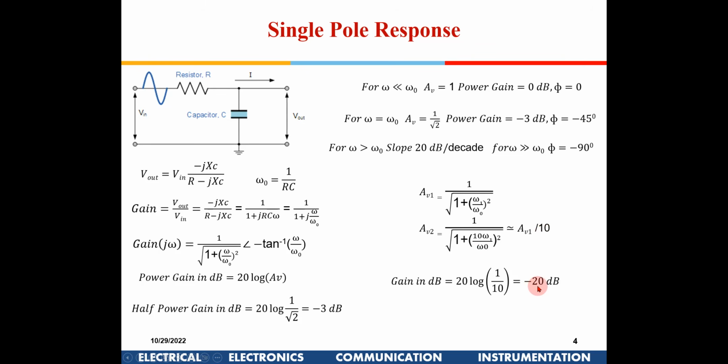And that in dB comes out to be 20 dB. So that is why we say if there is a single pole, the gain will fall at the rate of 20 dB per decade. In my earlier class also I kept on harping upon this. There will be 20 dB per decade. So you got where I got this 20 dB per decade, all of you? Is it okay?